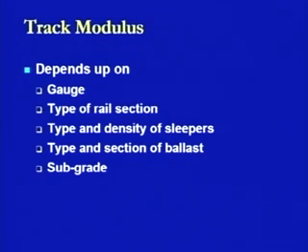Similar is the case when we talk about the ballast section. Ballast section is the third component, as we have seen previously, in a permanent way or a track. Here again we have different types of ballast materials which can be used. We have the crushed slag, the ashes, the cinders or the crushed stone aggregates. Obviously, depending on the type of the material and its load taking characteristics, we can define the track modulus. Better is the material, higher is going to be the track modulus.